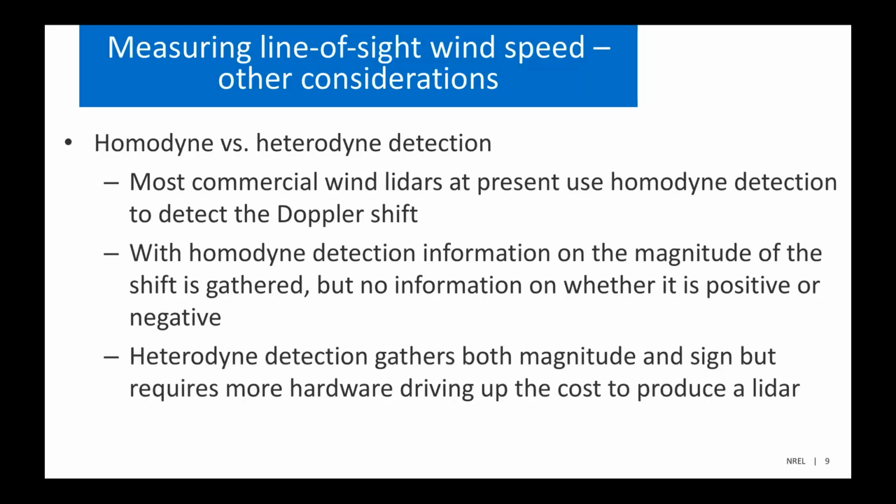With heterodyne detection, it is possible to gather both the magnitude and the sign of the Doppler shift, but it requires more hardware in the LiDAR, and it drives up the cost to produce that LiDAR.